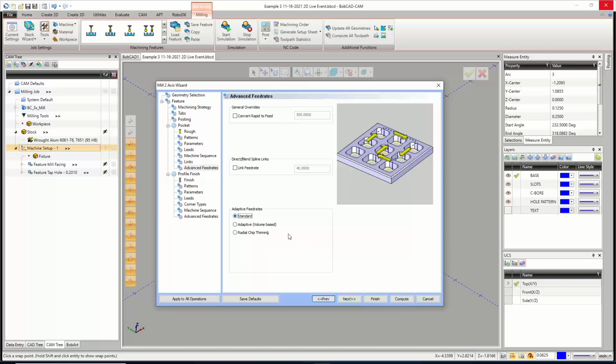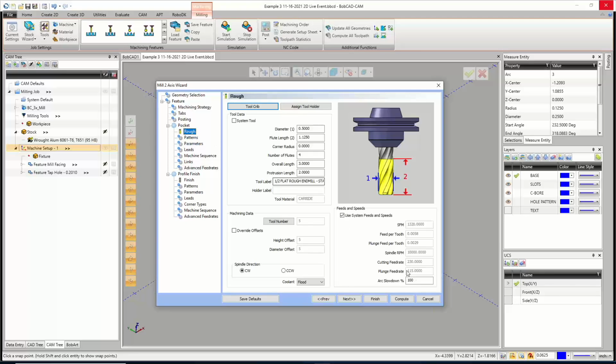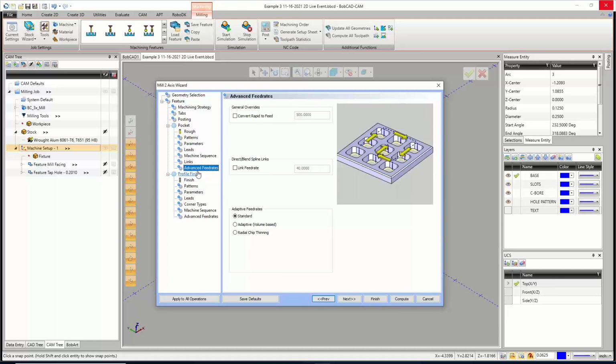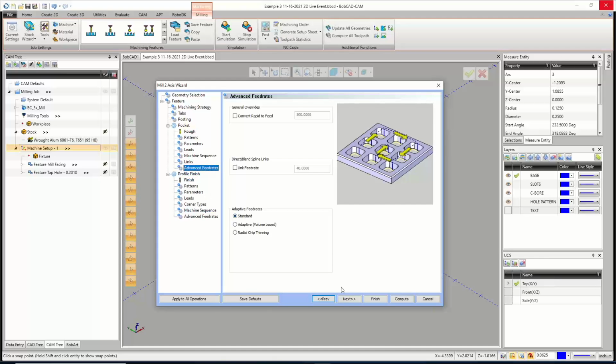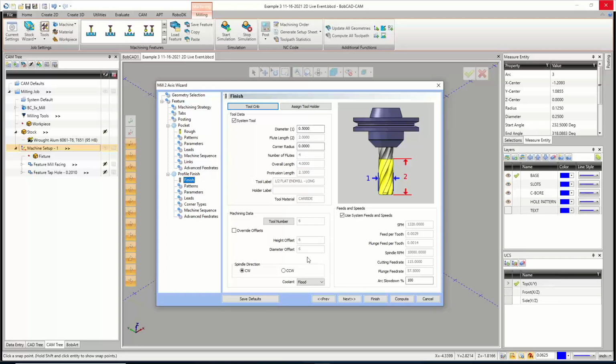But this one should be pretty consistent, and we're cutting it at 230 inches a minute because it's aluminum and carbide. Yeah, it's got some quick ones. It's the feed per tooth. It's a 4 flute. Yeah, we'll see. And then next, well, you can. I mean, 230 is not impossible. 1/2 inch deep could be a little bit crazier.